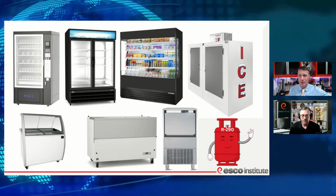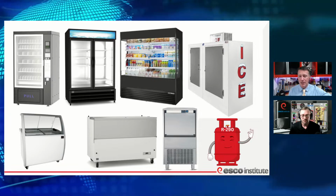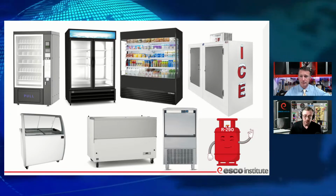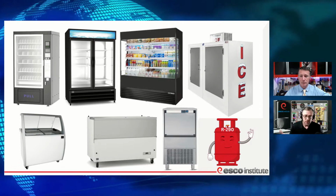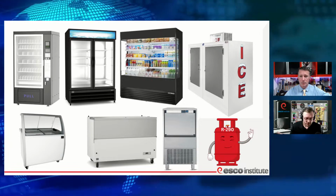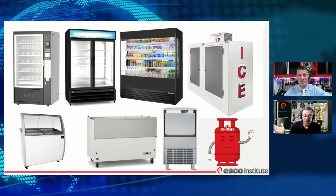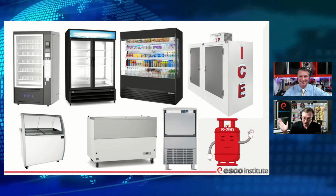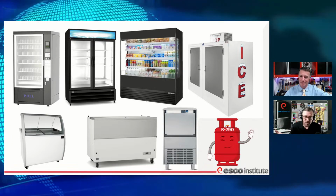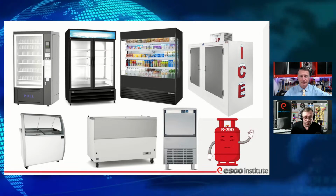Every one of these pieces of equipment on this screen are already R290 highly flammable refrigerant products out in the industry right now. I'm going to point out too that just because we're using mildly flammable A2Ls or highly flammable A3s, the refrigeration cycle is identical. In the cycle, superheat is still superheat. Subcooling is subcooling. We still critically charge by weight in a lot of this. The refrigeration cycle doesn't change just because the refrigerant is flammable.